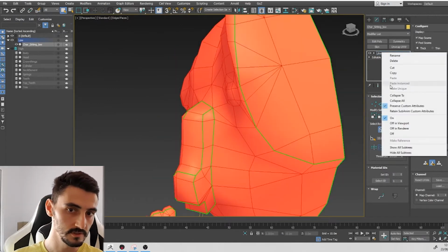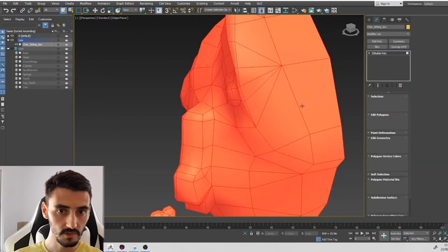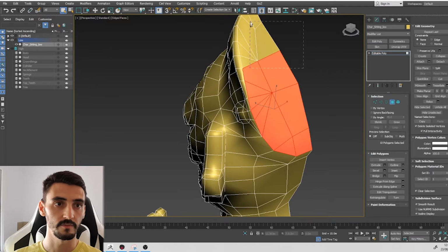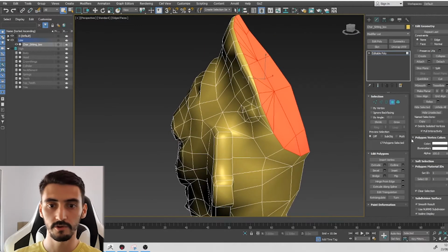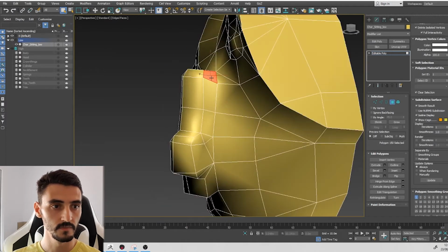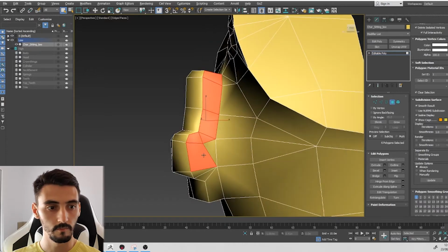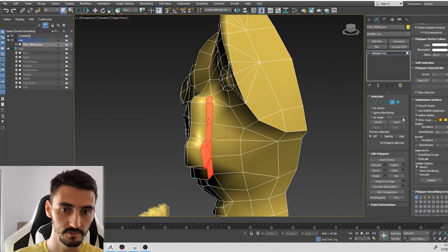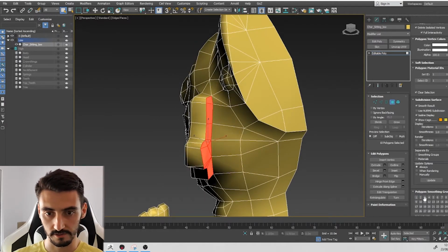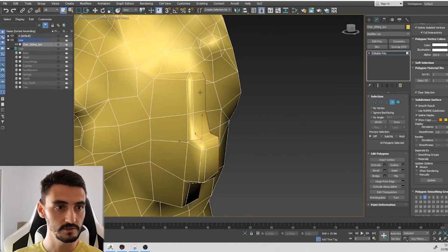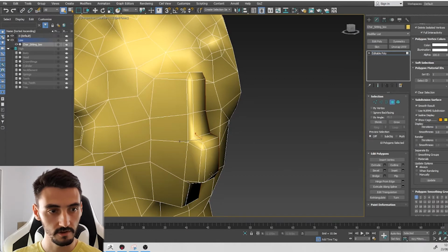So what I would like to do is collapse these, and then I'm going to select these faces. You can also select them from the UVs, but for me, this is easier. And then I'm going to apply a different smoothing group for these faces here. The lower your poly is, the lower amount of polygons you have, the harder the smoothing is going to be, so the more pronounced the errors. So I'm going to click third smoothing group over here, and then you'll see if I go back, how the smoothing changes right away over here on these edges.